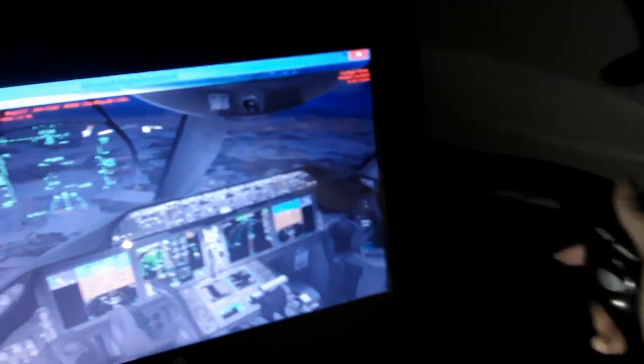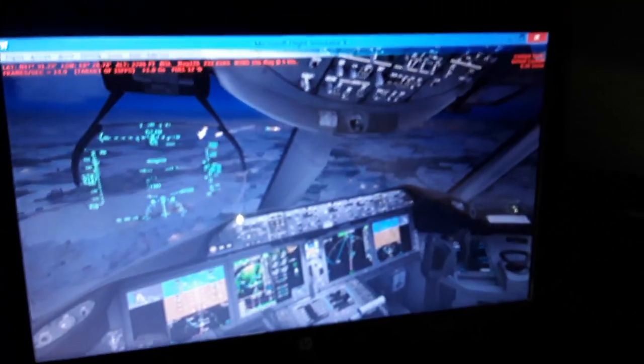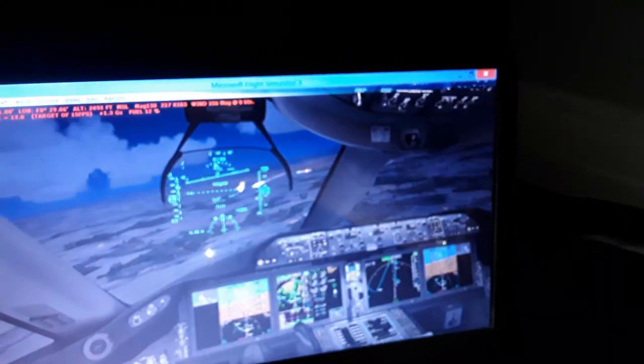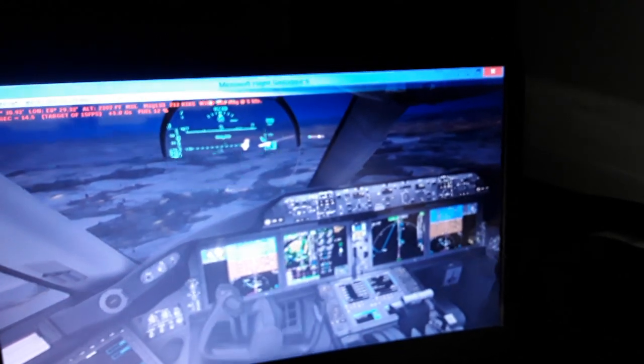So we have some side wind, some wind gusts we need to follow. We need to align the airplane with the side wind and the wind gusts, as you can see, because we have snow falling. So we're going to use cross controls, cross ailerons and thrust and rudder pedals.